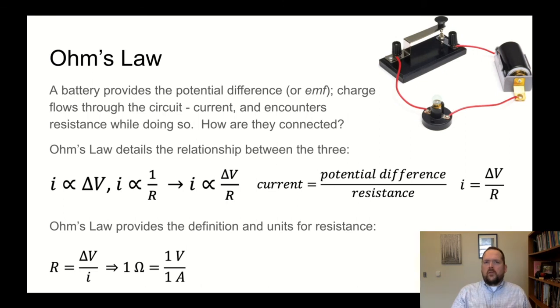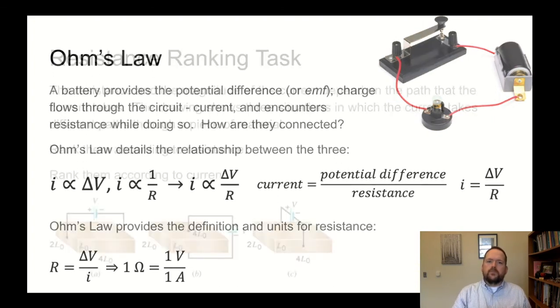So as charge flows through a resistor, however much of a drop that has in electric potential per 1 amp or 2 amp or whatever amount of current, that gives you how many ohms of resistance that resistor is considered to have. And 1 ohm, which is symbolized with the Greek capital omega, is 1 volt of electric potential difference per 1 amp of current.